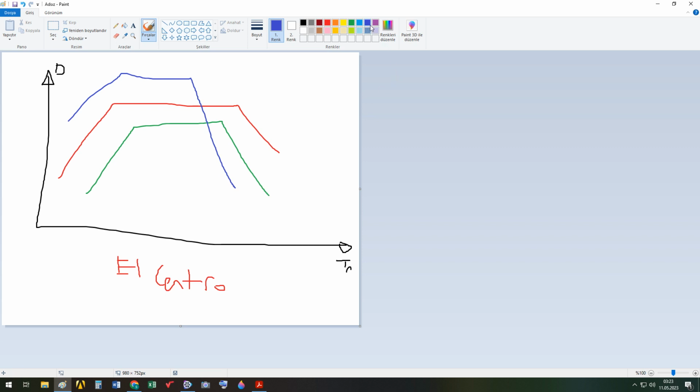For example, to be 100% sure that the maximum floor displacement will not be exceeded by earthquakes that happened in Chicago, not only because of El Centro or two other earthquakes, I prefer to use this response spectrum.